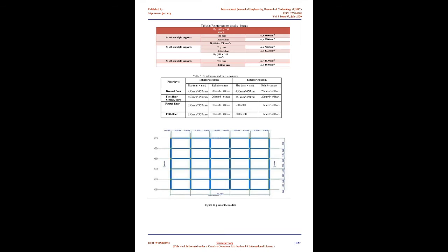2. Mani 1993: this researcher proposed the acceleration displacement response spectrum, ADRS, in which spectral acceleration versus spectral displacement is plotted in a curve, with the period T represented by radial lines. The crossing of the capacity spectrum and the demand spectrum gives the displacement demand and the inelastic acceleration. The capacity spectrum method was updated in FEMA 440, 2006.